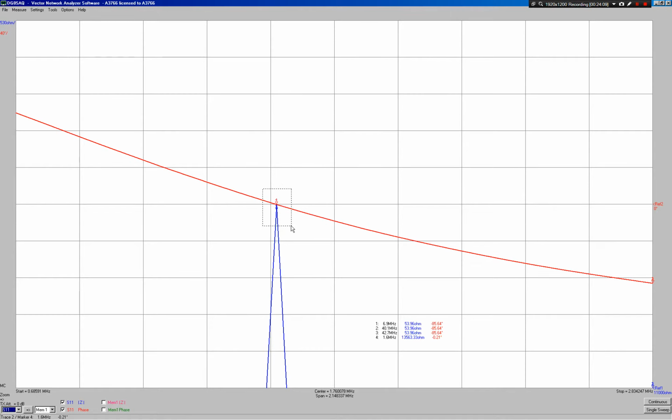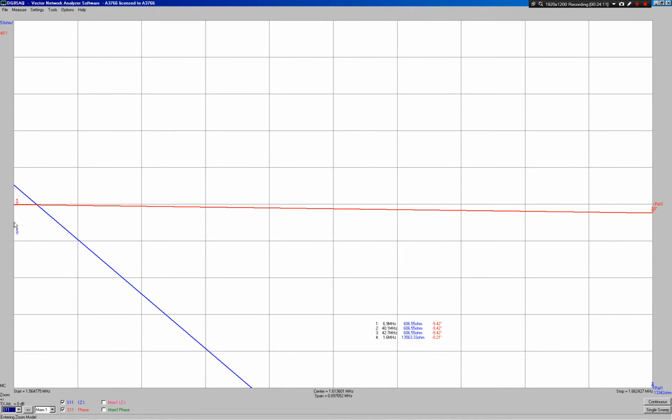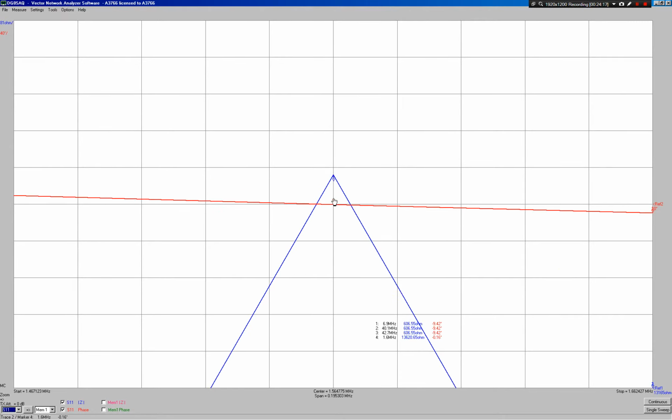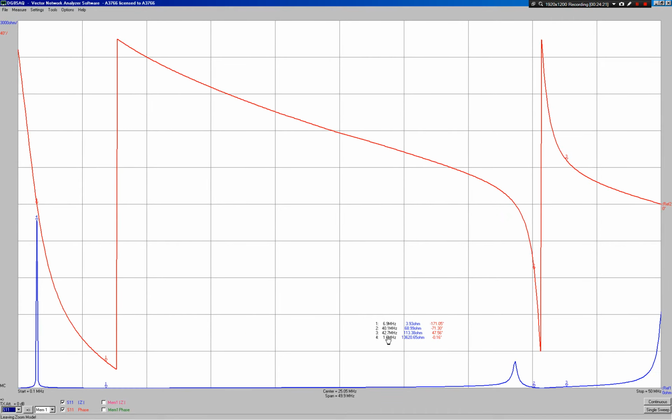It's very sharp, so it's difficult to get it there. And that's at 1.6 megahertz. So in other words, that parallel point loaded with 1300 picofarads of parallel capacitance across the inductance of the primary coil is going to push that peak right down to 1.6 megahertz.